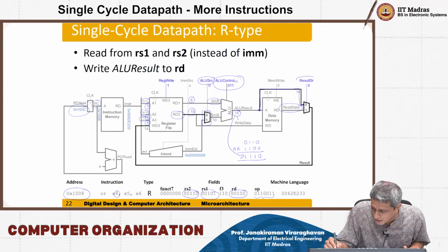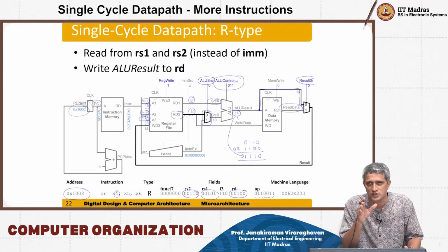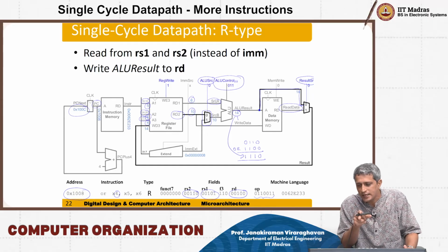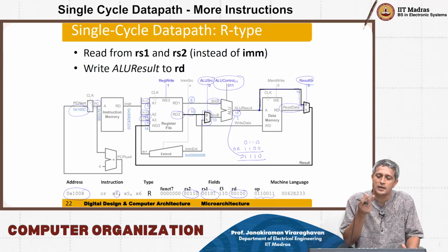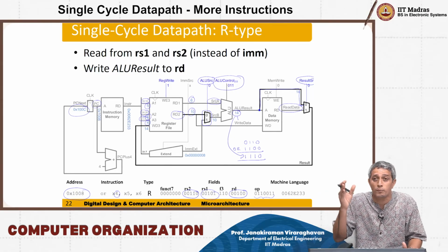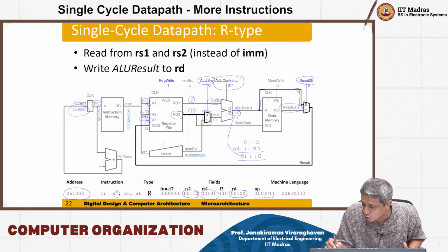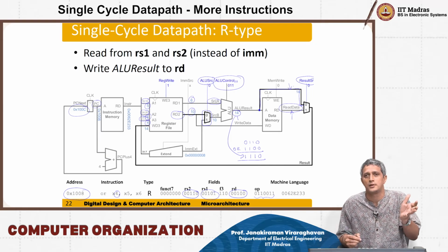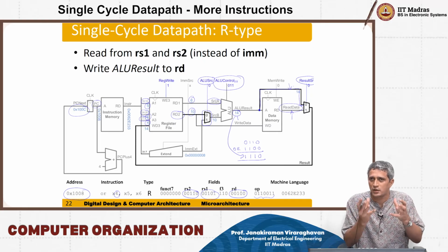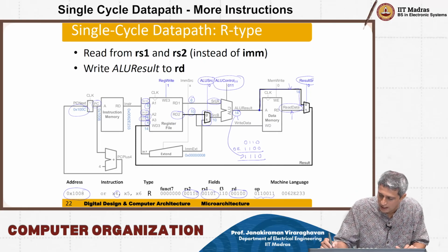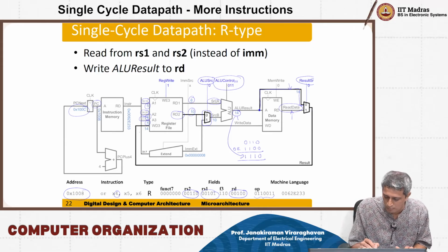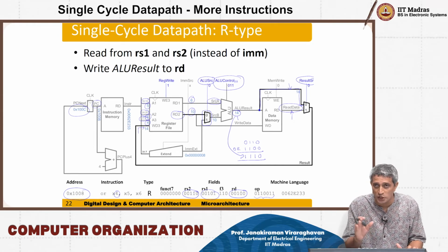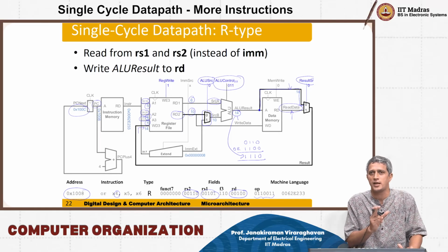And we have another control signal which is going to choose the result source, to tell us whether you are going to choose between the read data obtained from the data memory and the ALU result that you just calculated. That answer now comes back to this WD3 for writing back. So the 14 answer has now bypassed all this path and is ready.